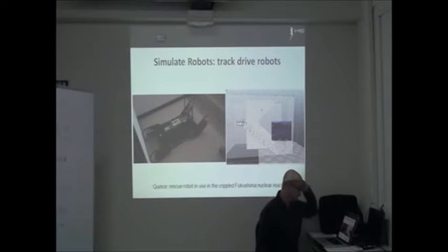So why are you doing that? Well, those are flippers, so you map them to buttons, so you have plenty of buttons. It's a Japanese robot and they are very good with video games, so they can handle plenty of buttons to move the flippers and the rest at the same time. But anyway, you need good training for that. So with this implementation, you just give the direction of the robot with a joystick, and the flippers will move accordingly, autonomously, in order to let you overcome some obstacles.